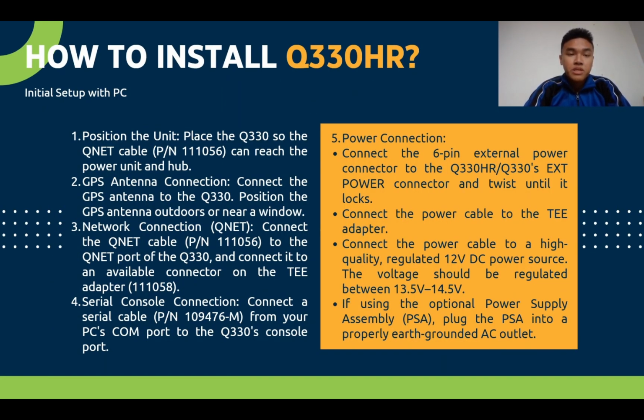Initial setup with PC. Position the unit. Place the Q330 so the QNet cable can reach the power unit and hub. GPS antenna connection. Connect the GPS antenna to the Q330. Position the GPS antenna outdoors or near a window.